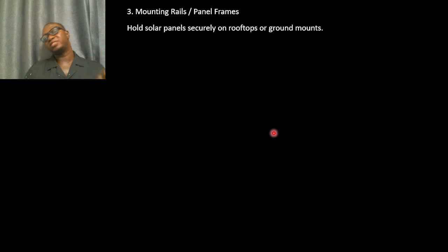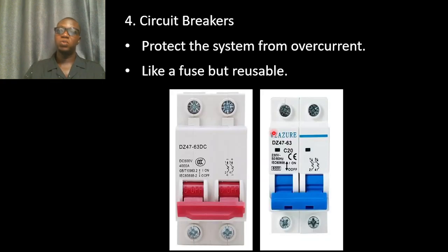When there is no clearance, your panel tends to get hot very fast. But once there is clearance, air flows under the panels, and this brings a cooling effect. And when the panels are cooled, they produce more than when they are hot.